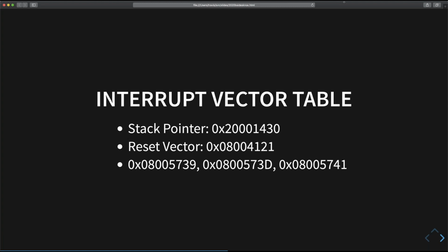And we can use a logic analyzer or a chip-off approach with components to check pieces of the firmware in order to confirm that we have it loaded to the right location.